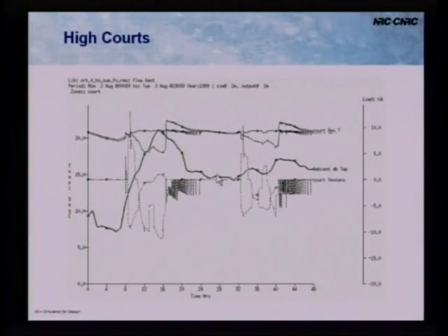Looking at the night ventilation scheme, this is only a 2-day simulation, but what we've selected here is a period where we've got cool overnight temperature, then it gets warm during the day, and then we've got an overnight where it stays relatively mild, and then mild during the day. So we've got two very different boundary conditions, weather days here, but our performance is still reasonably good in both cases in terms of resultant temperature in the court. It stays within the control parameters that we're looking at there.